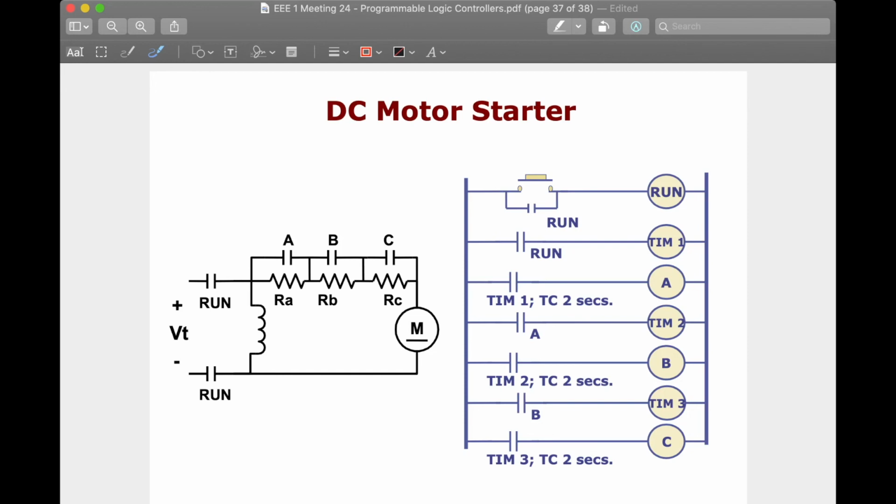So what we do is attach switches to the current limiting resistors. Here, in this case, we have a three-stage current limiting resistor. We've attached three resistors, and we run switches in parallel to them so that we can short them out, so that there's no resistance preventing the motor from operating at its full capacity. To implement this, you can use the PLC.